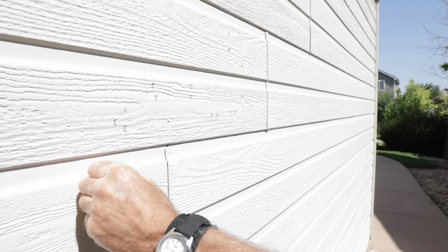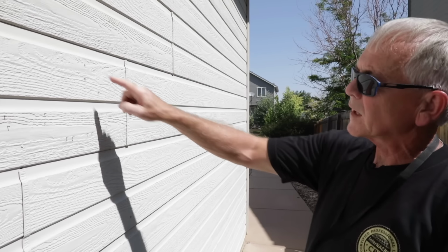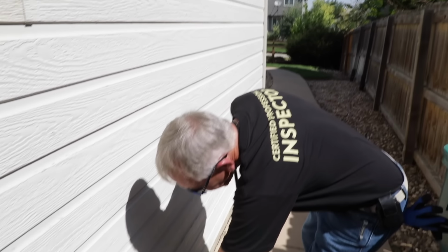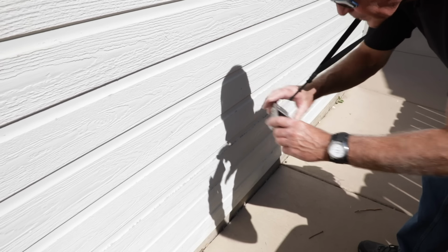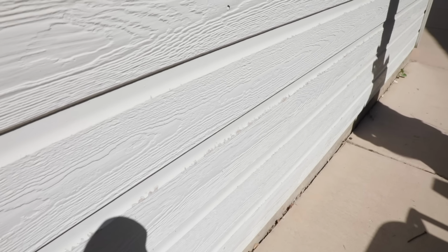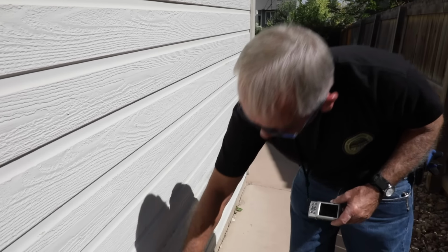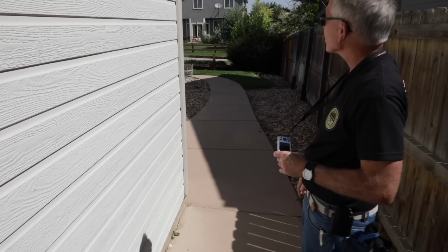We've got a lot of, I don't know, little nails or something here that I'll probably note in the report that these get pulled out and sealed. We got some unused holes here as well. It's possible somebody had something hanging up here. We've got a little bit of paint chipping here and peeling. I'll probably note that in my report. We're not really required to inspect or make any comments about any cosmetic damage, but in this case, not having this painted could actually hurt the siding. So I think that we should at least note that for a paint touch-up.